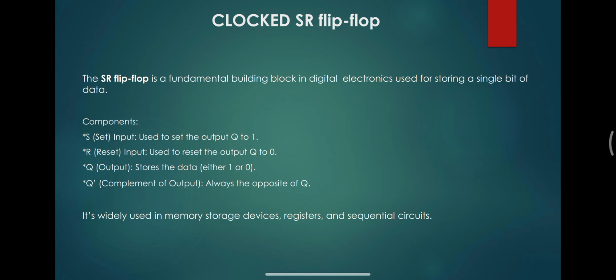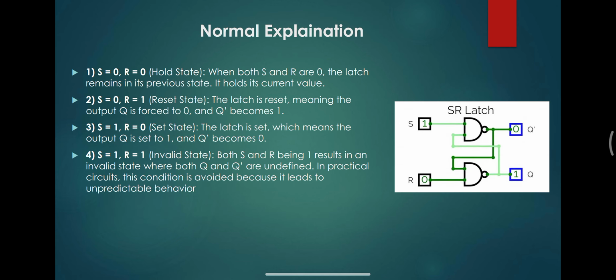The SR flip-flop is used in storage devices, registers and sequential circuits. There is a normal SR flip-flop circuit in this presentation. If S and R are both 0, the latch remains in its previous state. Here is the whole circuit below.